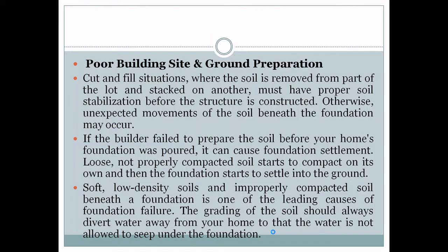Soft, low density soil and improperly compacted soil beneath a foundation is one of the leading causes of foundation failure. The grading of the soil should always divert water away from your home so that the water is not allowed to seep under the foundation.